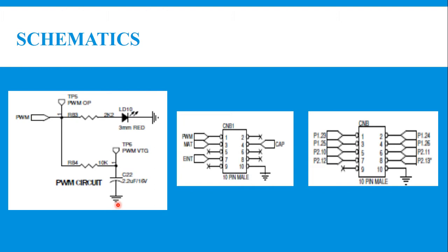There are about 7 match registers supporting the PWM output signals. Here in the program PWM1 block number 1 is used. There are multiple registers that will be used, such as IR and TCR. Once I move into the program, I'll explain each register along with its function.